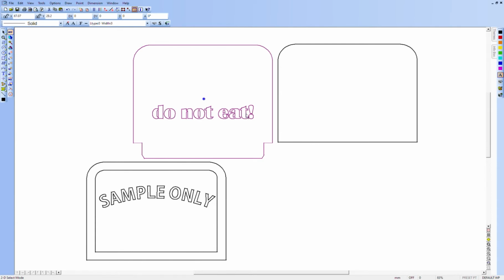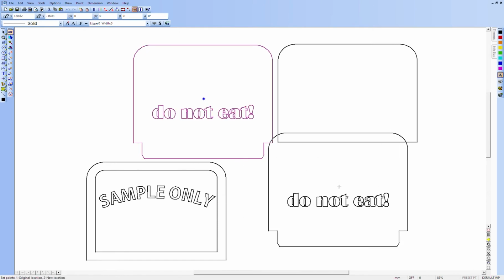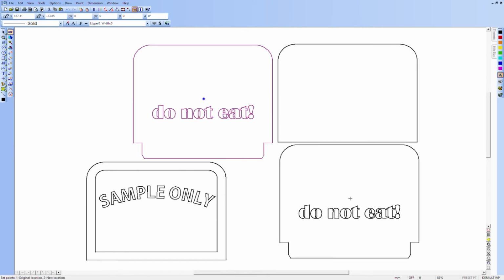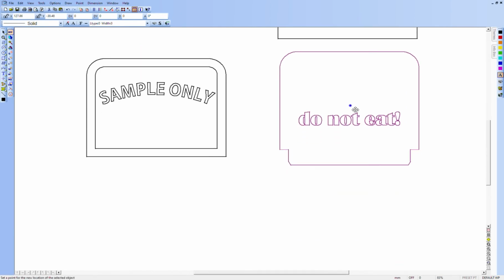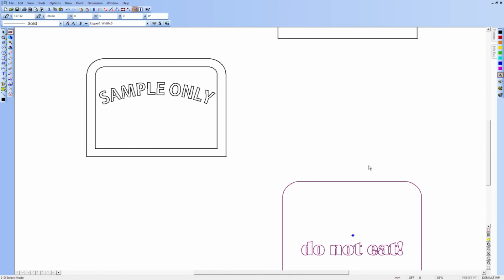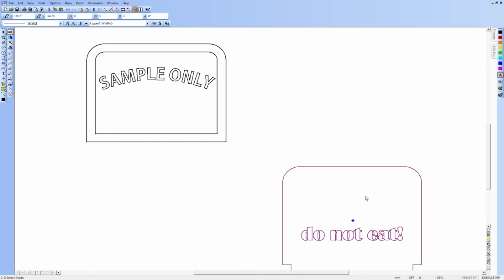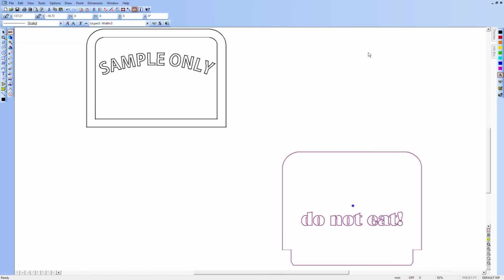So depending on the shape of the sheet of wood we're cutting from, we may want to arrange them differently. Let's assume we have a skinny, vertical sheet of wood to cut from. So, we're going to move this part below the other one to make a vertical stack. We can see right away that this arrangement is actually not the most efficient, because these radiused corners mean that the straight line on top is shorter than that on the bottom of the other piece. Same thing if we flip it and mate the tongue to the back piece.